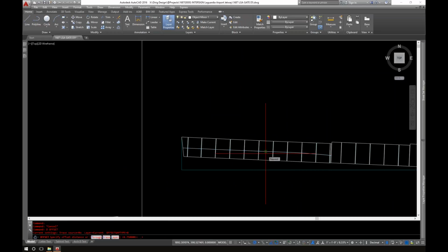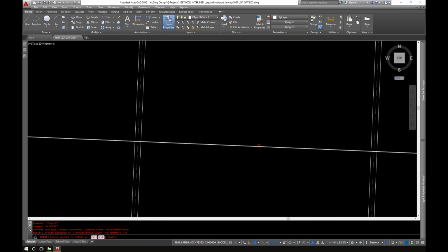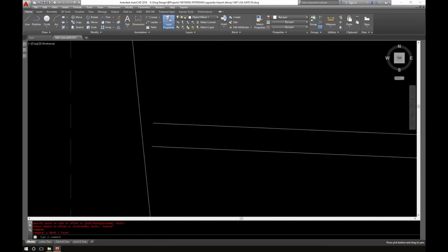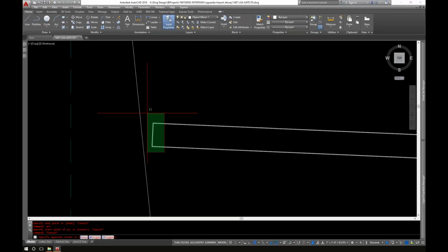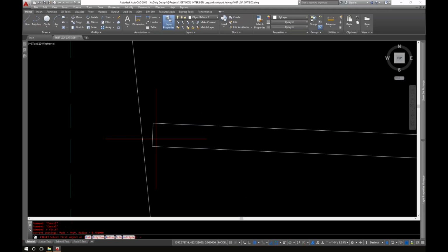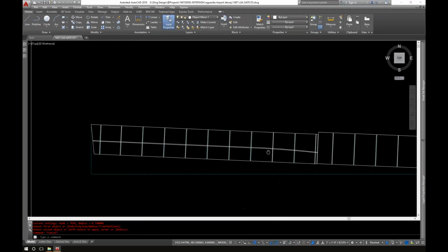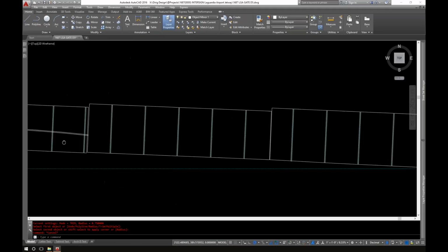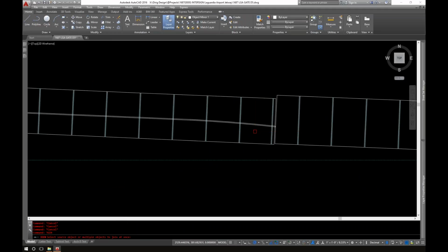Okay, and now I'm going to offset 3/4 of an inch this way, and 3/4 of an inch this way, and delete this one. So now I have this, 1, 2, and this I don't want it to be a polyline, so fillet radius. The polylines, they have some hard times communicating with other polylines sometimes. And again, this is going to go up to here, fillet radius, and I'm picking the midpoint to there, and the midpoint to there. Okay, now I'm going to join all of this.